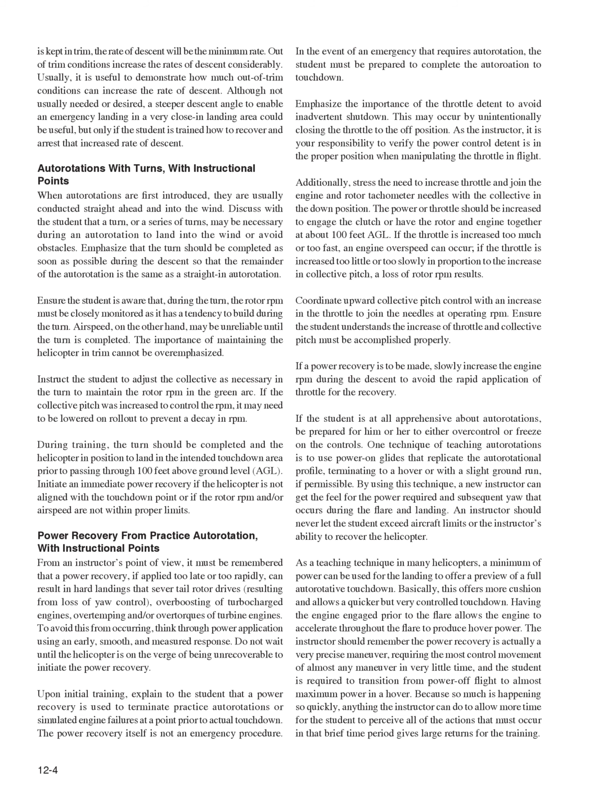Ensure the student is aware that, during the turn, the rotor RPM must be closely monitored as it has a tendency to build during the turn. Airspeed, on the other hand, may be unreliable until the turn is completed. The importance of maintaining the helicopter in trim cannot be overemphasized.